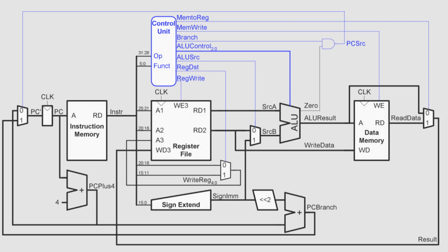These techniques can only get us so far. Other avenues must be explored, such as switching off parts of the CPU that aren't in use. For example, the register file isn't typically accessed in each cycle, at least in some types of circuitry. And in many cases, the values of particular registers need not be updated every clock cycle either. In light of this, it is beneficial to gate the clocks of these registers.